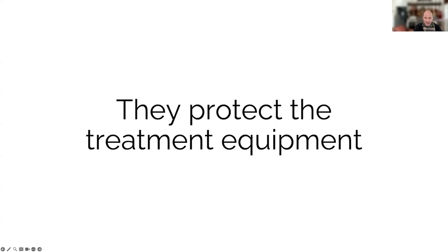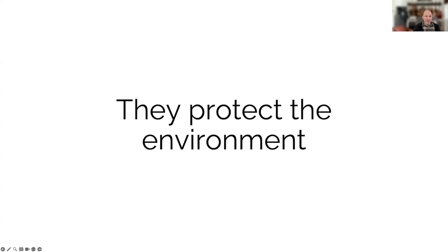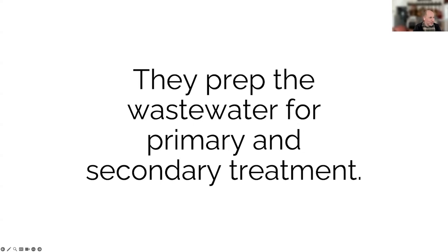They protect the pumps, they protect the valves that could get jammed or broken or made less efficient if larger materials were allowed to pass through to them. And in turn, of course, that protects the environment, because clogged pumps and filled-up channels can lead to inadequate treatment or in some cases overflows. So preliminary treatment helps you comply with your permit requirements as well. Even though there typically aren't biological processes going on there, essentially what you're doing is prepping the wastewater for the real primary and secondary treatment.